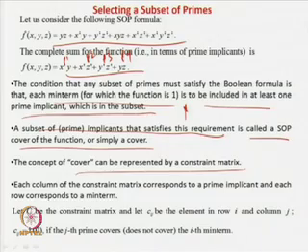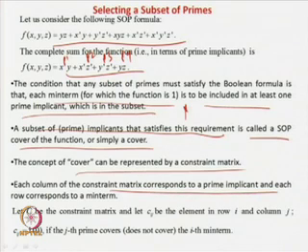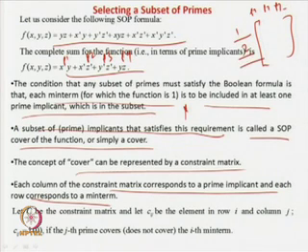Now, till now it was circuits, Boolean expressions and all, but now we will see that while we are solving this computational problem, we do not need to think about circuits and all. It can be represented by a constraint matrix. So what is that? Each column of the constraint matrix corresponds to a prime implicant, and each row corresponds to a min term. We will have a matrix like this: here will be your prime implicants P1, P2, P3 and so on, and here will be min term 1, min term 2, min term 3 and so on. Whatever the min terms are, they have to be here.